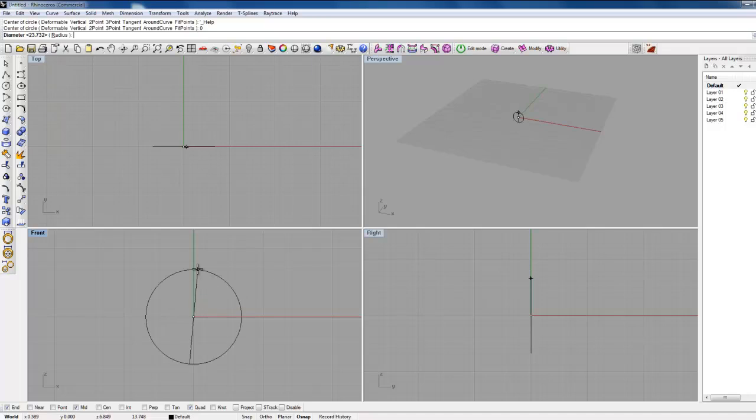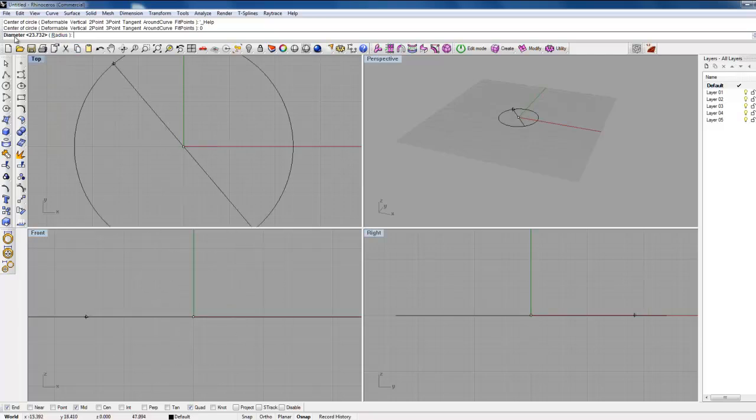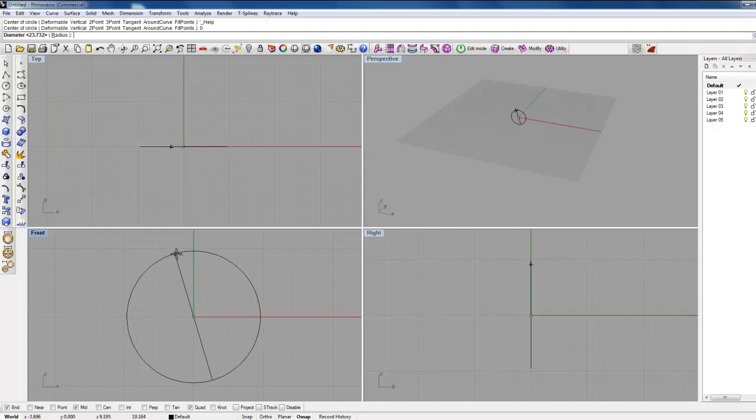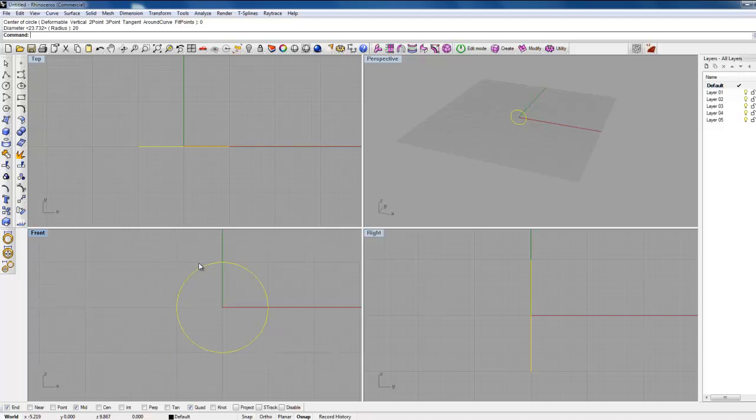So now we need to work a size out, so let's do 20 mil, big man size ring. If we type into here, we've got it set to diameter there. If we type 20 into there, press enter, that'll give us a circle of 20 millimetres, which is great.